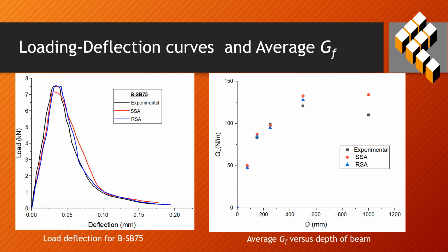Then what we have observed is that fracture energy keeps on increasing as the size of the beam increases, and then suddenly it becomes flat, which we can consider here for 500 mm to 1000 mm depth of beams.